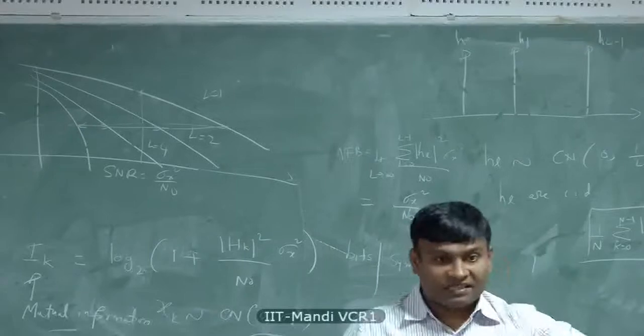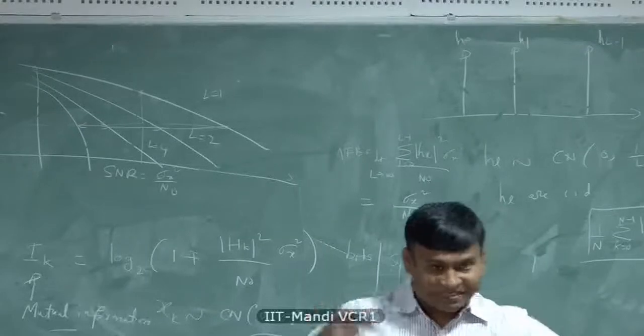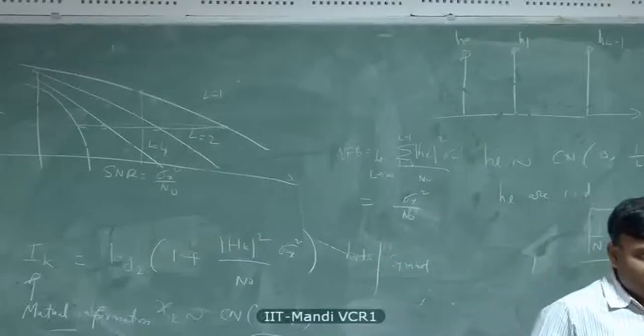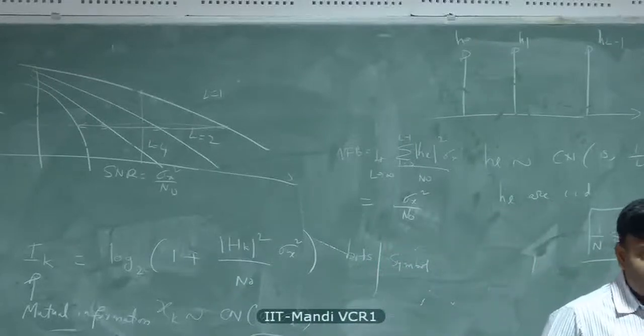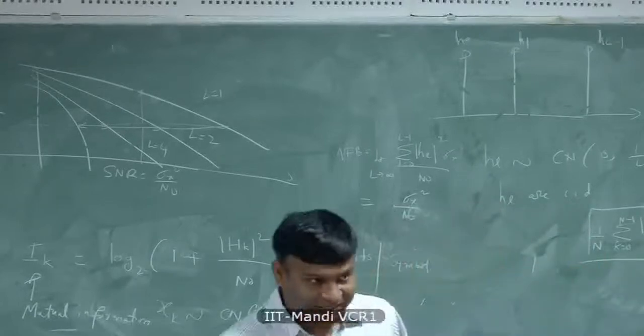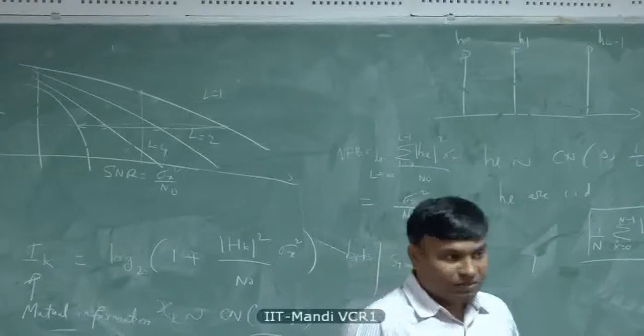It's almost like line of sight with some fading. I mean, equivalent line of sight with fading. It's not really line of sight, there is scattering around you. So a 30 kilohertz channel is a flat fading channel. And then you may say, oh, the channel doesn't have much multipath to exploit. Well, yes, there is not much multipath to exploit.